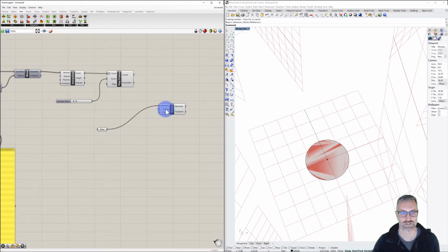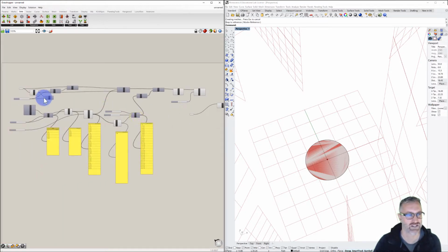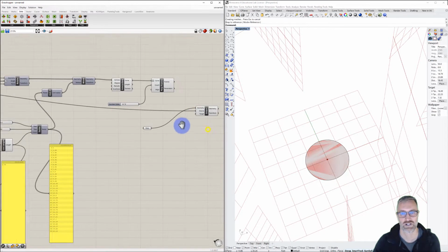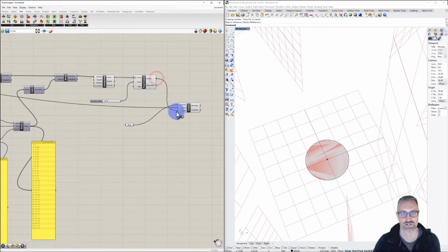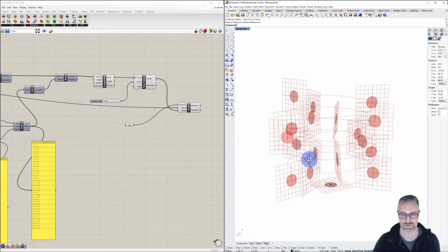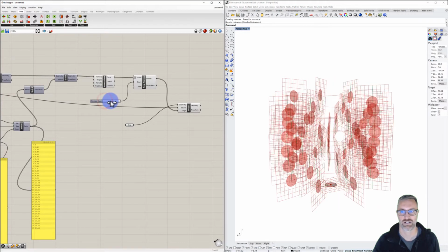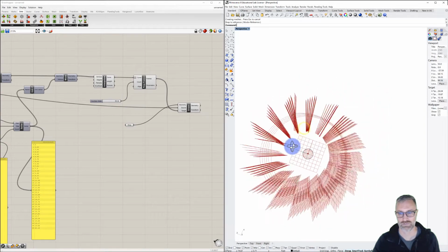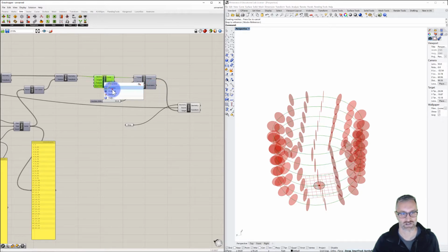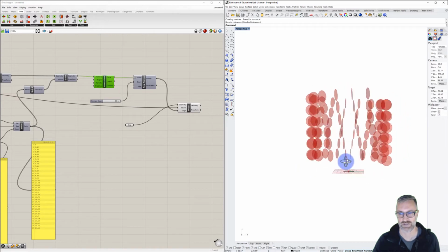What we're going to do is use the source, and that source is the initial plane. That plane is what we have as our XY plane all the way back at the beginning. So pull and we'll drag that over to the source. And then our target will be our frames. If we zoom out, now what we see are those points, or that planar surface or circle, mapped to each one of those points on our helix. So we can hide our frames. We can even hide our interpolated curve.